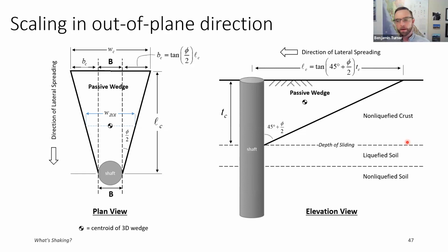link between our pile analysis, like an L pile, and then our slope stability analysis, which is 2D. So we have to take that pile resistance and represent it, per foot or per meter in the unit width out of plane direction. And there's not great guidance in this in the literature or in the design codes that talk about this.